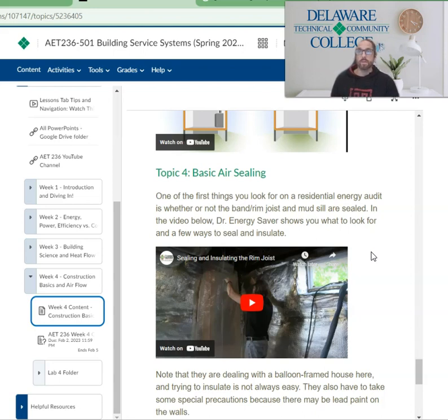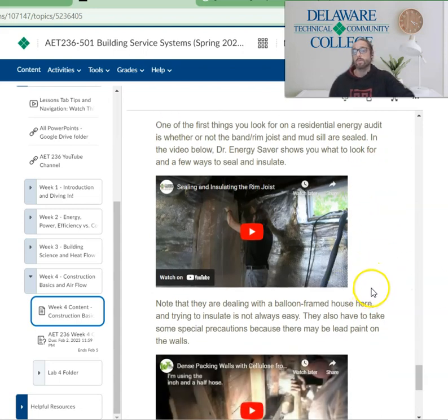Now, there are ways you can do it by putting positive pressure in a building. In a residential building, we don't do that. And so you have this air that's moving up, pushing out at the top, and at the same time, air is coming in at the bottom. So I have this cold air coming in, and at the same time, I'm losing warm air. That's sort of a double whammy of the stack effect. And so we'll look at how we help prevent or minimize that. Air sealing is the main way we do it.